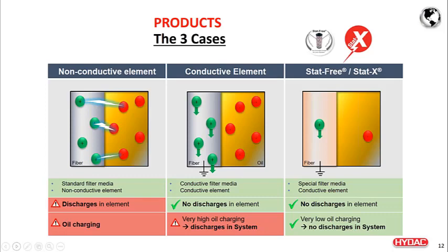And when the oil is passing through the filter element, that generated charge goes through the filter element and downstream of it. So the charge generated in the filter element is going to get grounded, and you will not have any discharge at the filter element level. But you're not solving the problem. The problem still exists, which is the charge in the oil.